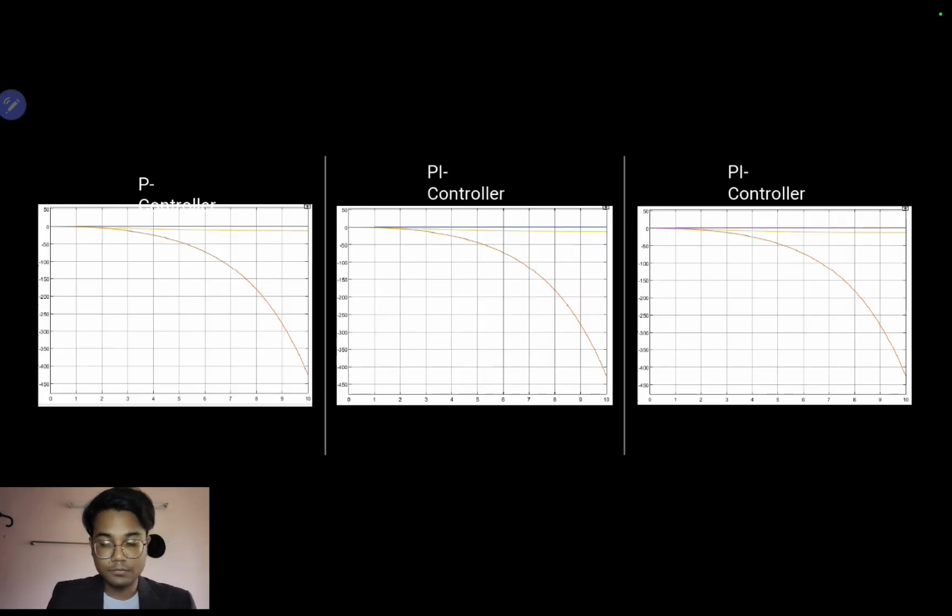We obtain the graph as shown here. That's all for me, and in conclusion, the Ziegler-Nichols method gives the best result compared to the Cohen-Coon method in this problem, and the best controller is PID because it gives the best performance, the best response curve based on the performance criteria. That's all for me. I'm Muhammad Irfan Shazmi bin Jamaluddin. A176956 is my matric number, and goodbye.